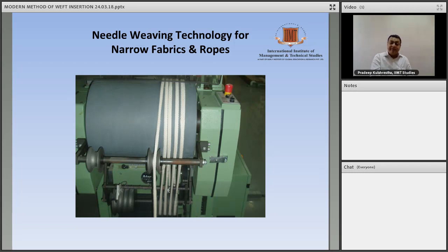Now this is weaving. The main advantage of this is that there is a provision for core and rope. Core is inside and rope is outside. So suppose we want to make the carbon rope. We will take the carbon inside, and we cannot hold it with naked hands because carbon is not good for health or our hands. So we'll put the polyester or cotton on the outside. We will hold it. So sheath, like onion, see, inside and outside layers.